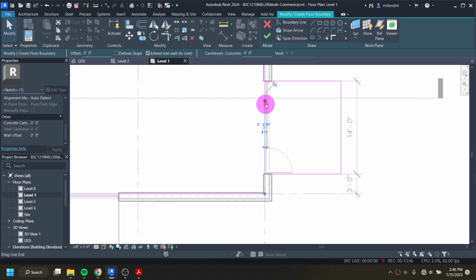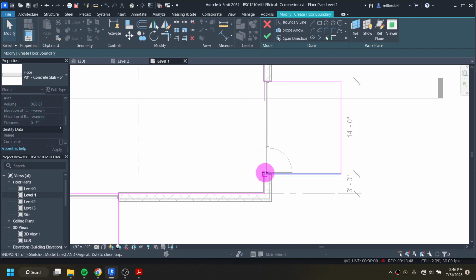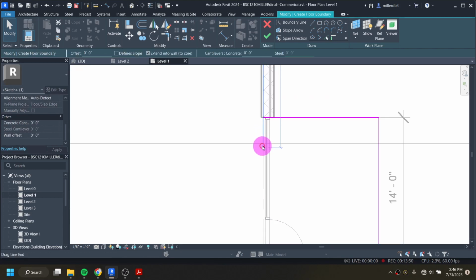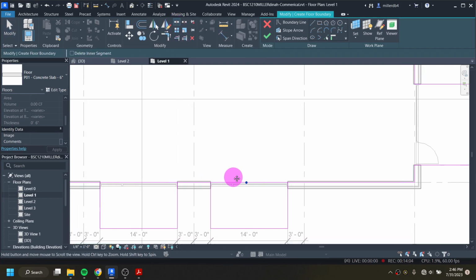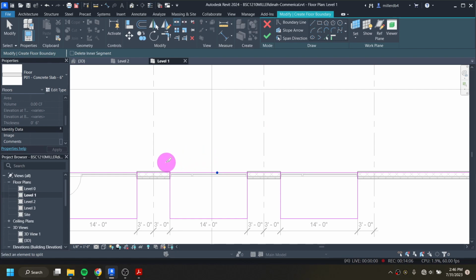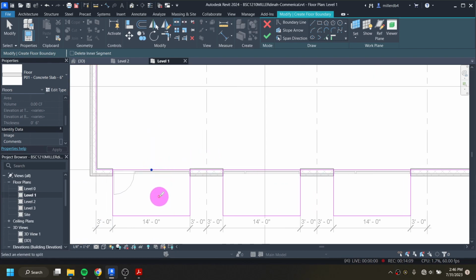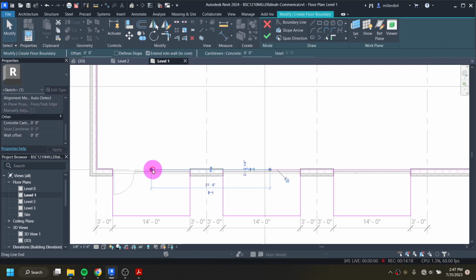And then I can hit escape a couple times, drag this one down to that endpoint, drag this one up to this endpoint. So that seems like our best bet. It seems like split with gap wouldn't let us, which is kind of a bummer. But we can do split element, slice this in half, click to slice this one in half, click to slice this one in half, hit escape about 3 or 4 times, and then we can drag these out.